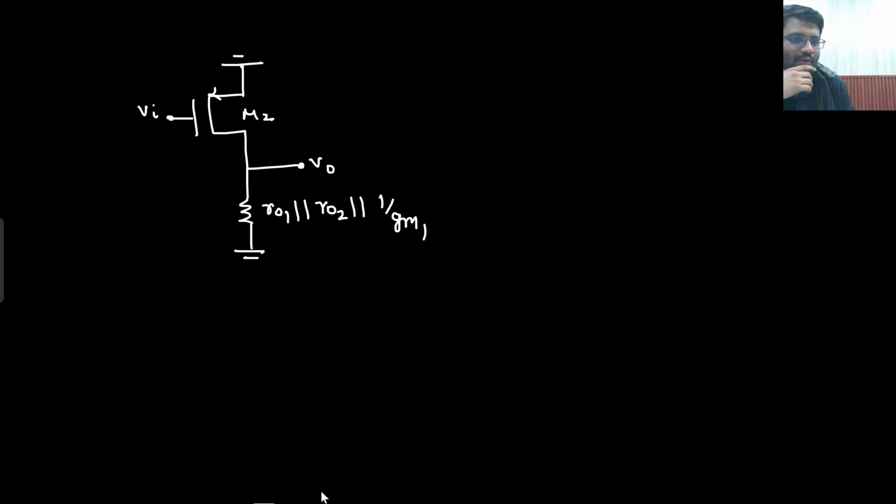Well and good. All fine. Now this is your V, this is your 0. Can you write down the current? If I want you to write down this current coming from upward to downward, what would that current be? That current would be GM2 times upward potential, which is 0 minus V in. Whatever the current that is flowing here, the same current would be flowing here as well.